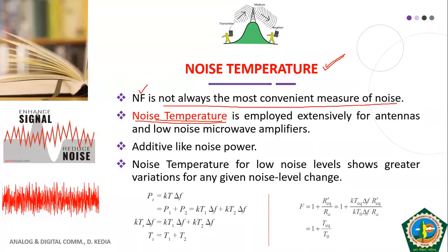Though noise temperature is again having mathematical significance, it gives us the same kind of impact of noise as it actually exists. So the noise temperature concept for noise performance is employed extensively in case of antennas and in case of low noise microwave amplifiers.